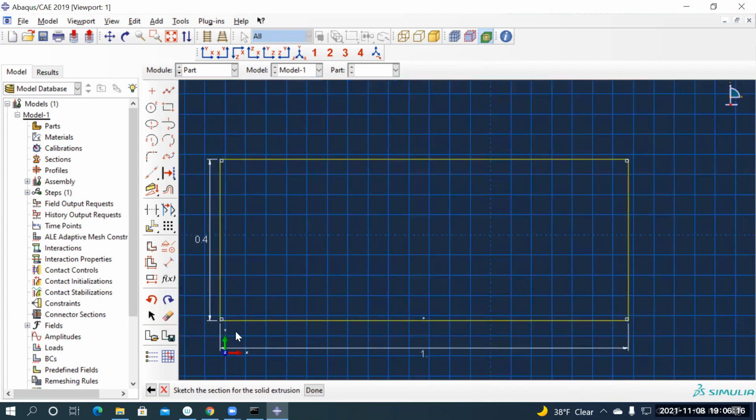As you have observed last time, I've used the loft option. If I'm planning to loft from one plane to another, I need to be careful with the origin. So we'll create the origin. Select a construction line, a vertical construction line. If you place your mouse, it says construction line. Hold on with your left mouse and select the vertical, and when it's asking for X, Y, type in 0, 0. And that places the vertical line at 0, 0.